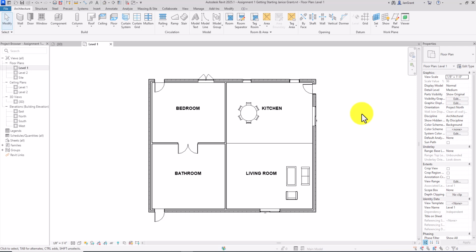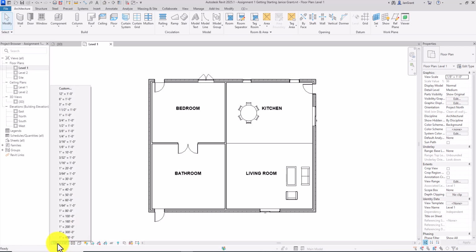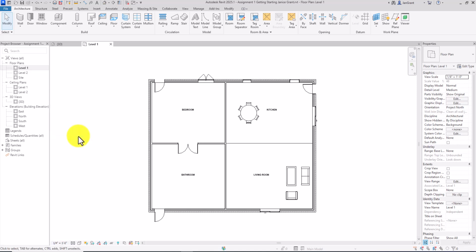There are a couple of other things I want to mention to you. Just like using this icon to look at the layers inside the wall, the scale that's next to it, 1/8 inch right there, is determining your text height. This is for 1/8 inch, but take a look at what happens when you select 1/4 of an inch. You see how the text gets smaller because your drawing is going to be bigger, because it's 1/4 inch equal to a foot when you print it. So we had 1/8 inch, then 1/4 inch.